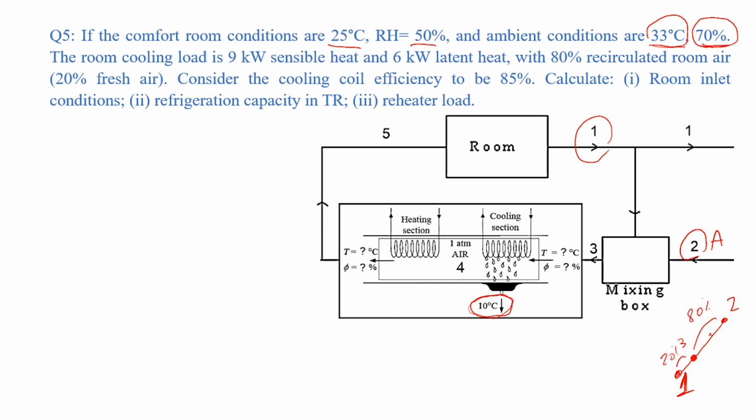So we can use either the fresh air percent or the circulation percent for the calculation. Fresh air percent is 20%, which is 0.2. Ambient in this case represents the fresh air. Again, like in the Y mixer, we take the far side, which is 0.31. This will be T3 minus T1 divided by total T2 minus T1.